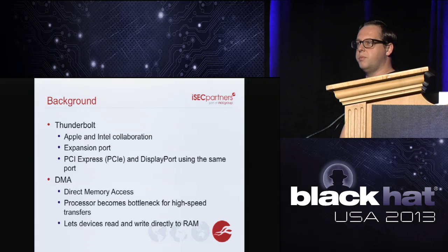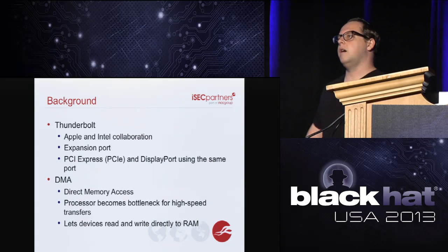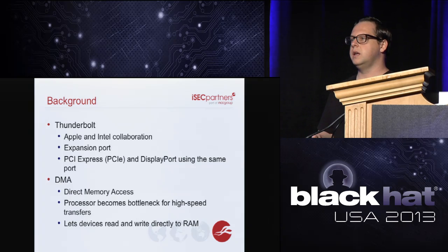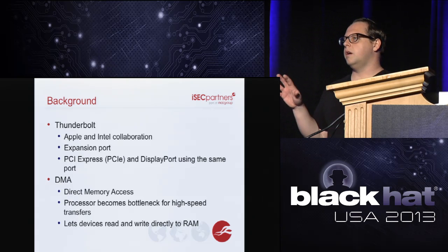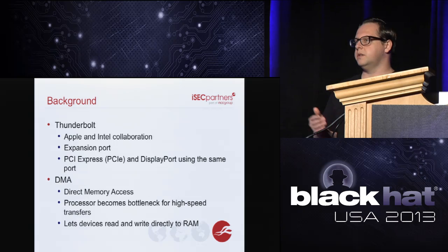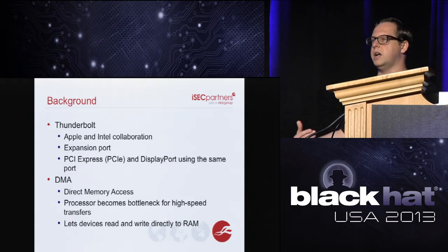So what is DMA? It stands for Direct Memory Access. Back in the day, when a device needed to access memory, it did what's called programmed I/O. A device would contact the processor. The processor would take the address that it wanted, store it in a register, then go fetch that memory and come back. So the processor was the middleman.